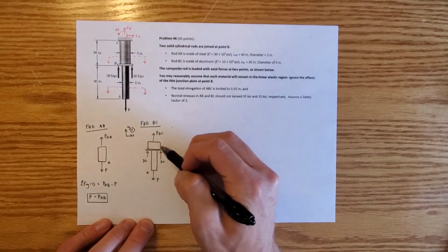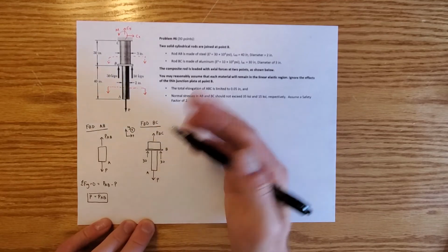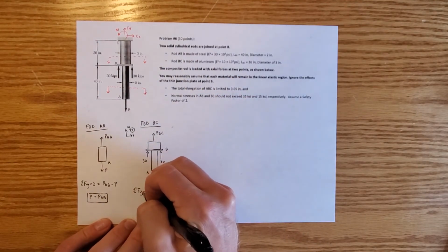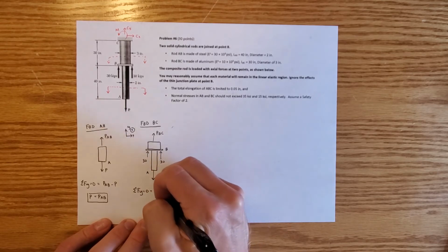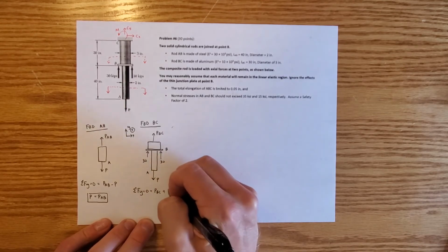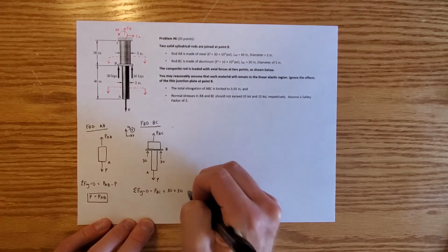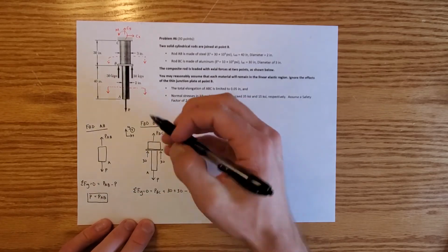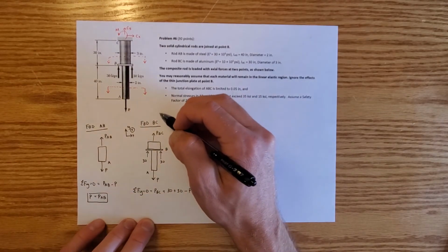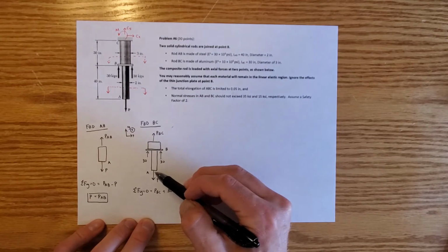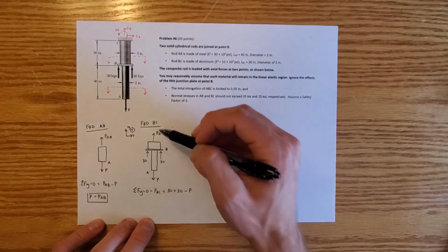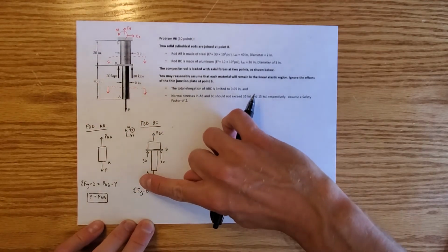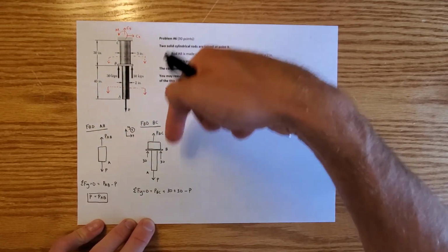We see we've got 30 kips going this way, and we've got a P going down. So if we sum the forces in the Y on this particular free body diagram, what we'll see is PBC plus 30 minus P. So we don't know whether PBC is actually going up or if it's going to point down, because it's possible that if this P got really large, the PBC would be up, but if this P was 0, for example, PBC would be 60 pointing down.